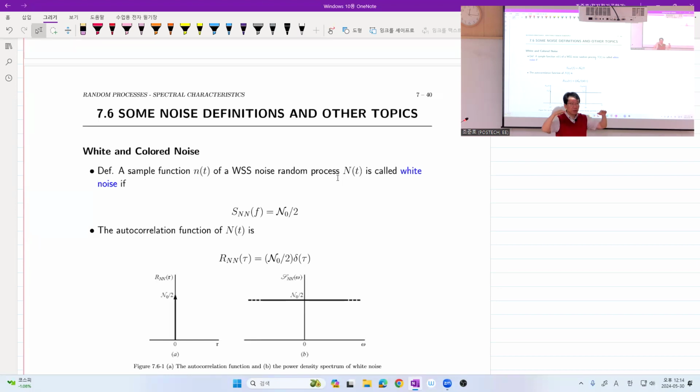So we have bumping around of the electrons, even though they have a mean velocity. And that is amplified and observed by the receiver after amplification. And this thermal noise can be well modeled in the frequency domain as an almost flat spectrum signal.